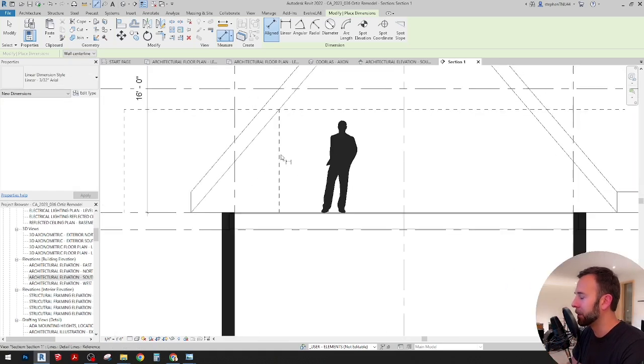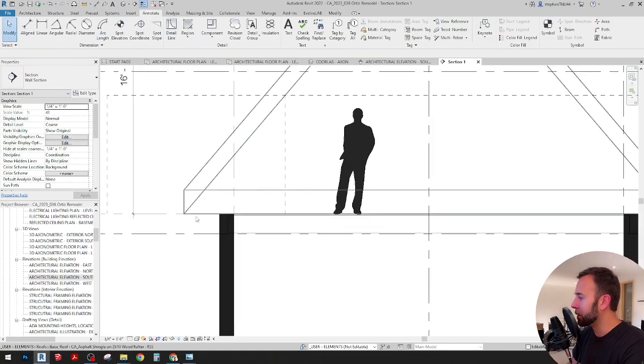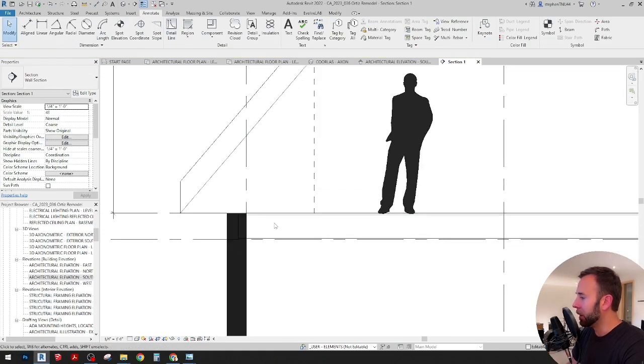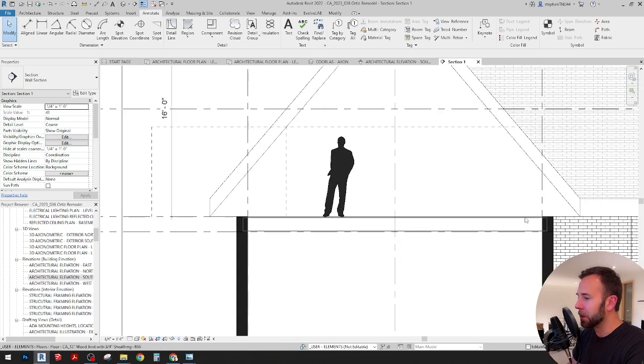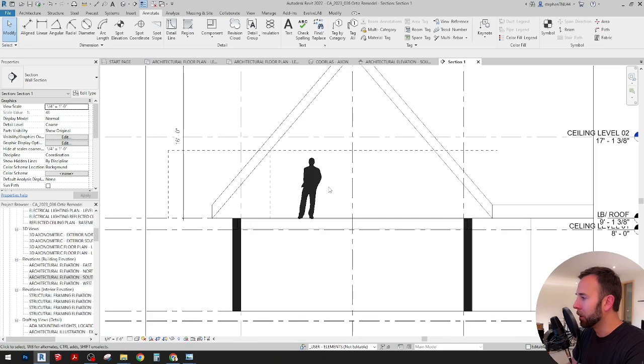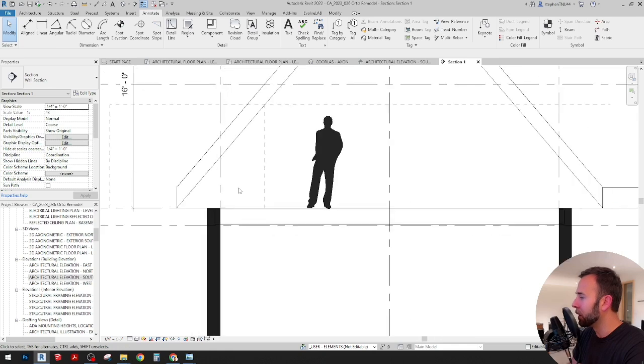So you can do some low closet storage, which would be nice along the perimeter, and that is what we talked about. But you don't have to set the wall there. Obviously, there's more usable space here, and if our joists are flying out and capturing the edge of the roof there, that's again, for instance, why we like to set the bottom of roof a little lower. You get a little more usable space basically down into that corner there.